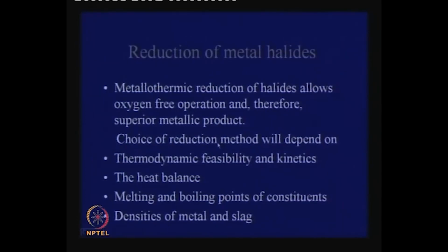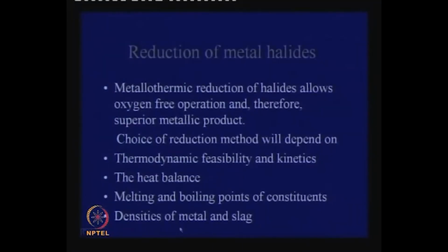First of all, the feasibility in terms of free energy change in the reaction, and in terms of enthalpy change, so that we can tell whether the reaction itself is making available sufficient heat. If not, we have to put in another reaction, a booster reaction, that supplies heat. We have to worry about the melting points and boiling points of reactants and products, to see whether it allows easy handling or whether it is possible to do things under normal conditions. We also have to worry about separation of metal and slag for cleaner recovery.